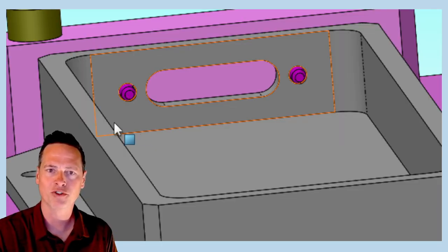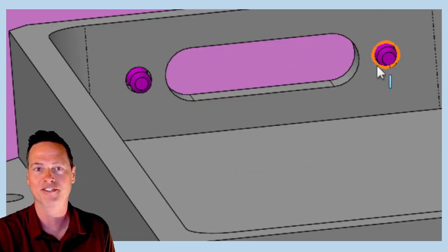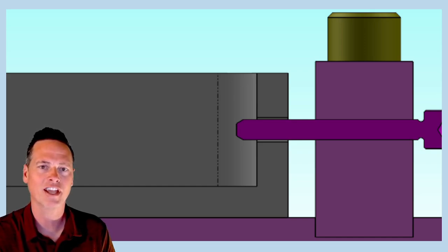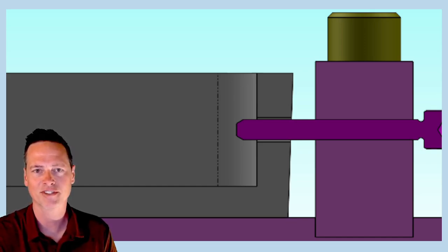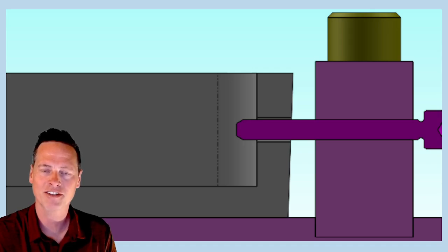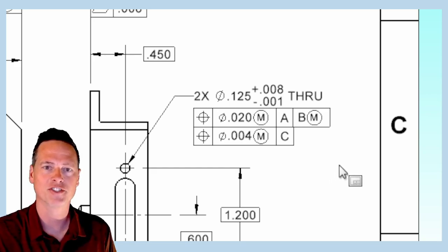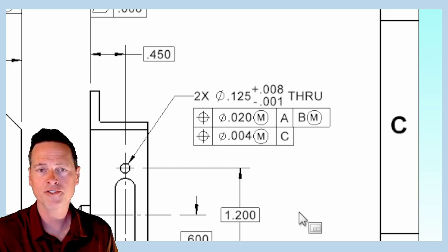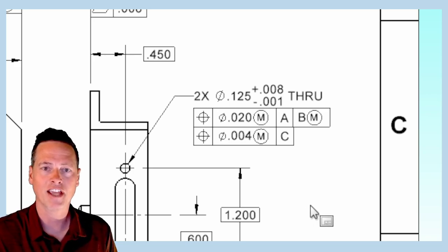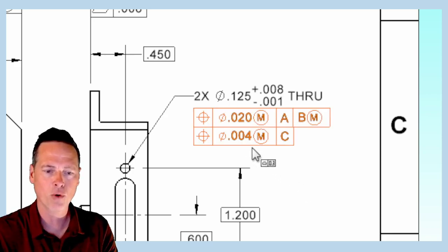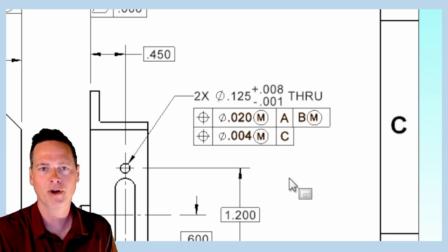It is good to have some control though, at least just to keep them located on, for instance, this slot here. Check this out too. This is what happens if we have a little bit of orientation deviation on that datum C surface. It doesn't really have much of an effect on this inspection. Great. So how about this lower frame position tolerance on these .125 holes? This one is 4 thousandths diameter at MMC, referencing datum C primary. And just a quick note, we still have the .124 MMC, and then we subtract 4 thousandths this time, so we have 120 thousandths virtual condition, .120.